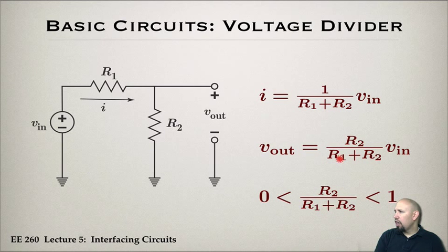If R1 is large, what does that mean? That means whatever circuit we've combined to get the R Thevenin has a large, what's called output impedance. So this quantity here, which we refer to as the Thevenin resistance, is sometimes called the output impedance. And so you can see how it affects the overall circuit by making the denominator large here and making this overall number small. So if we have small output impedance, that's a good thing, generally speaking. So that's what this is called, output impedance, output resistance.